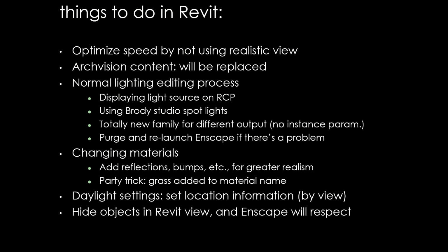First of all, those of you who are working on laptops, you may start to experience some slowdown on your computer because you have Enscape running and it's chewing up all of your graphics memory. So you can optimize the speed of your computer by not using realistic view in Revit. I have found that makes a tiny bit of difference, but if you have like 10 views open in Revit and they're all on realistic view, then you might actually start to notice some performance differences.